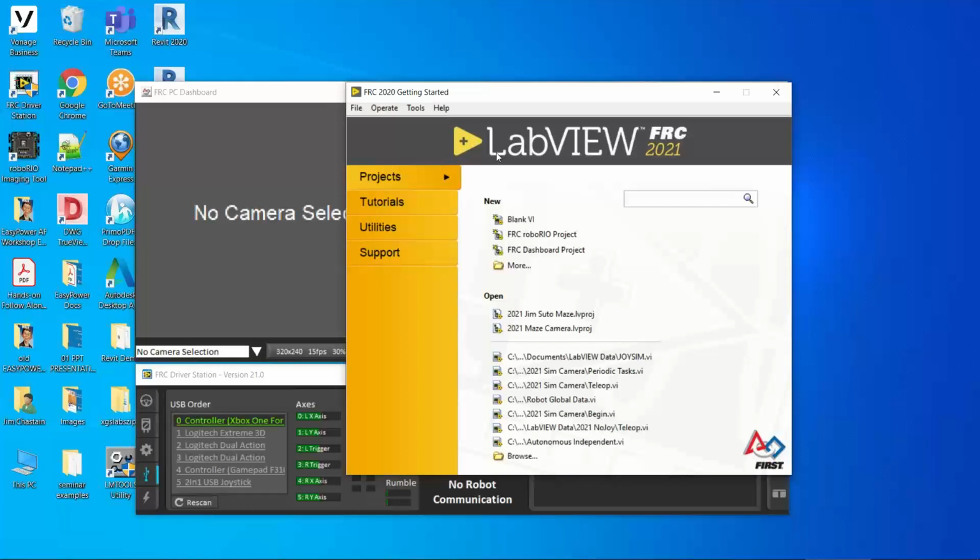And in FRC robotics, that ends up being in the actuator controls. If you don't update the motor drive controls every 100 milliseconds, they stop because of the Watchdog Timer. So if you've got a program that locks up for a second, your robot's going to stop about the third second you're on the field. So anyway, that's fun stuff to look forward to.